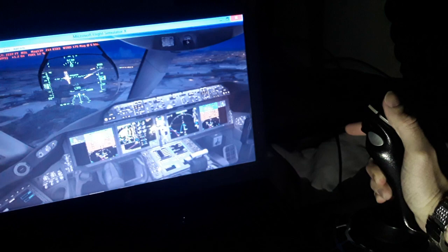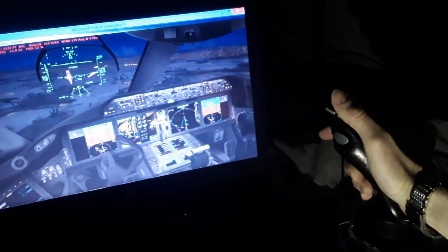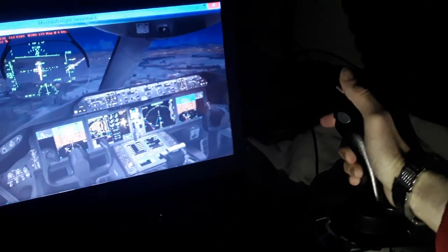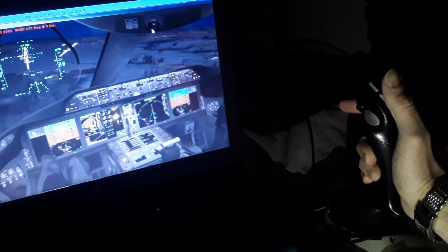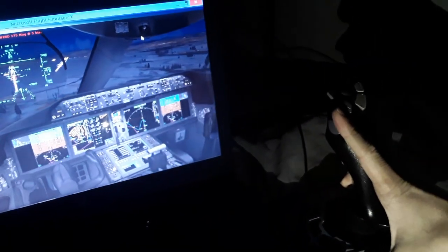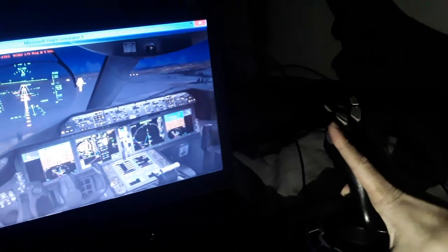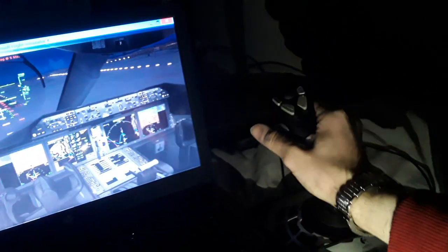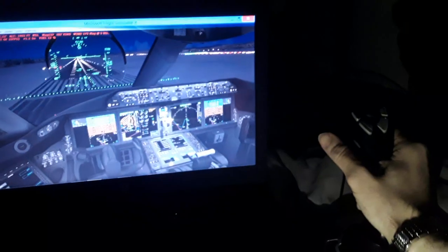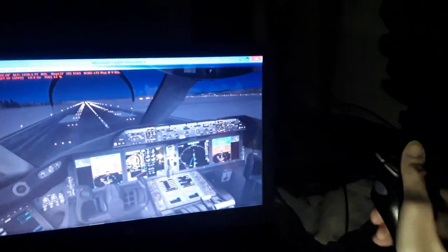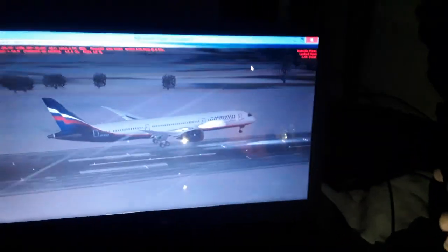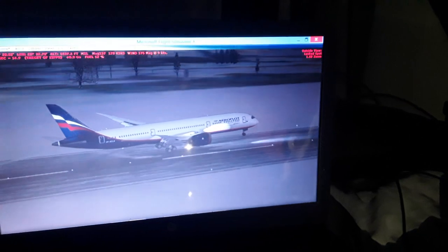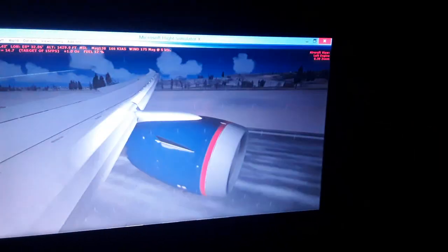So we have some side wind we need to align using all the flight controls, aileron, spoilers, control wheel, control column. Also the rudder pedals, use a lot of rudder for align with the runway over here. Use a little bit more thrust whenever needed. So we're gonna be aligned here. We have the flare here, as you can see, flare for touchdown, flare the aircraft, and touchdown, beautiful touchdown. Here we are.